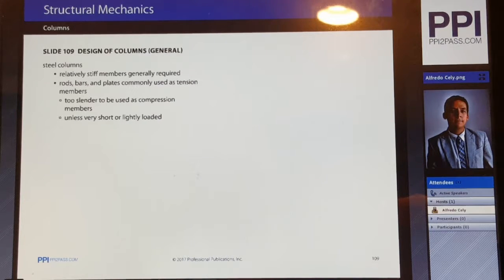Load carrying capacity varies approximately inversely with the slenderness ratio. There are three general modes by which axially loaded compression members can fail. 1. Flexural buckling, which is also known as Euler buckling, which is the concept that we just reviewed. 2. Local buckling, where one or more parts of the member cross-section fails in a very small area. And 3. Torsional buckling, where lateral movement and twisting occurs.